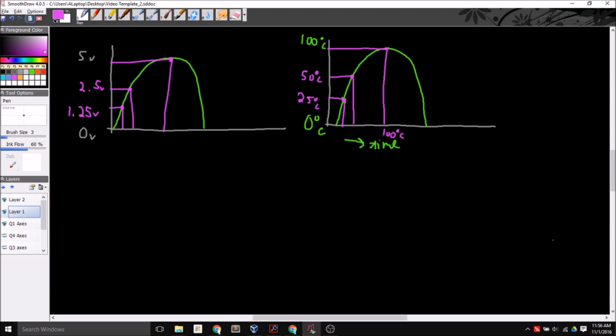And that allows me to do things like multiple if statements, or even what's called a case statement, so that I can say if the voltage is somewhere between 1.25 and 2.5, maybe I don't necessarily want to add all this energy to continue boiling the water. Maybe I want to keep the temperature at that point. So what I would do is, after I get from here to here, I want it to heat up at 100% speed that it can possibly heat up. But then I want to make sure that it stays within this range.